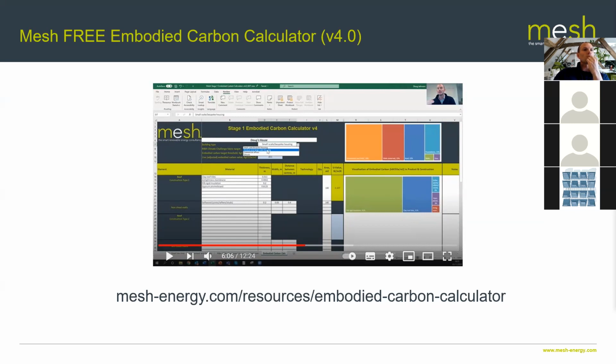In terms of material conductivity, you do have more nuances with some materials. Can you get mineral rock? You can get mineral or rock wool at 0.032 to 0.037. That's really important to note: every material, and there are loads of EPDs against materials, has a band. There's never just one fixed value.